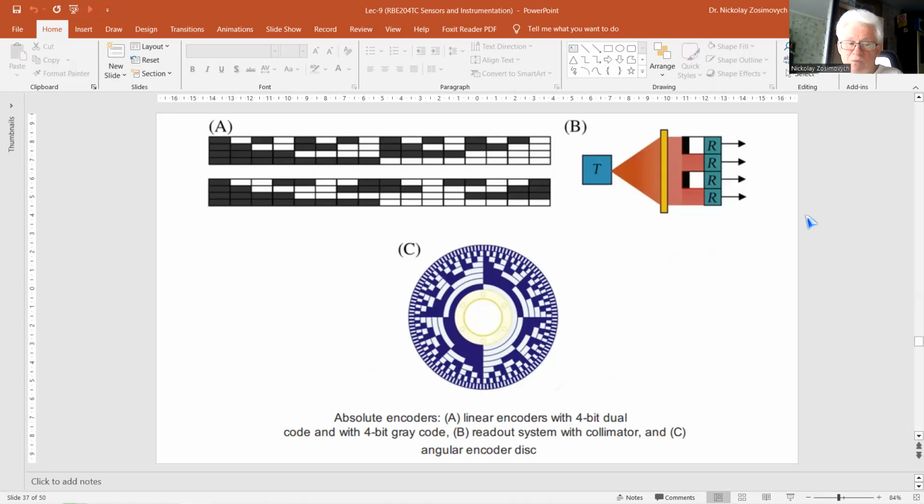In the transmission mode, the encoder consists either of a translucent material like glass, plastic, or Mylar, covered with a pattern of an opaque material, for instance a metallization, or just rubber, for instance a metal plate with slots or holes. Two basic encoder types are distinguished: absolute and incremental encoders.